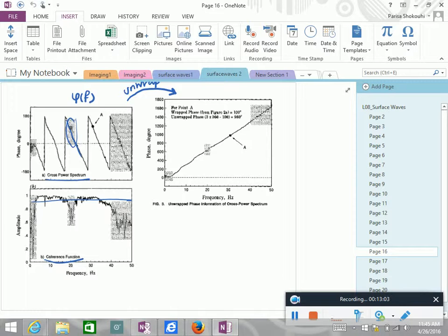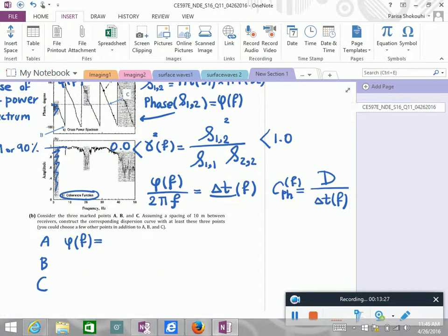It means you basically take this 360 degrees, you go here and then you add that, you unwrap the phase. And this is what you get. The phase you want to put in your equation is the unwrapped phase, because that's how many degrees or radians it has taken. Now, if this was given in radians, you would put 2 pi. Now it is in degrees, so you have to divide it by 360, right?